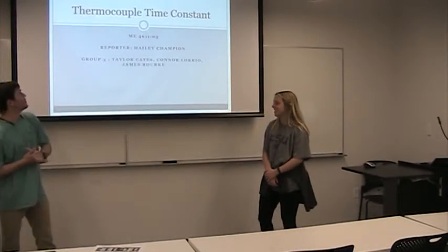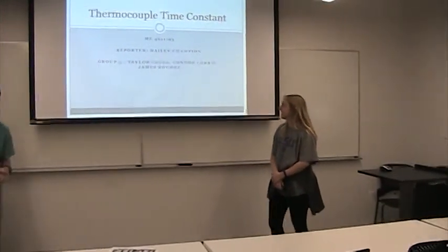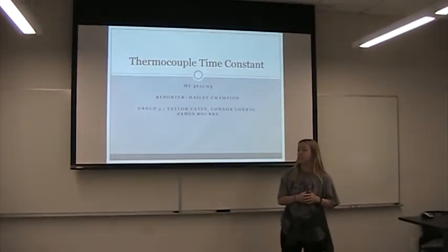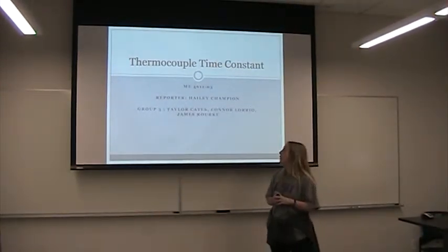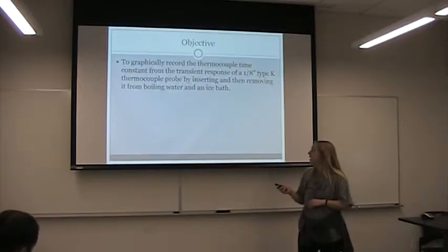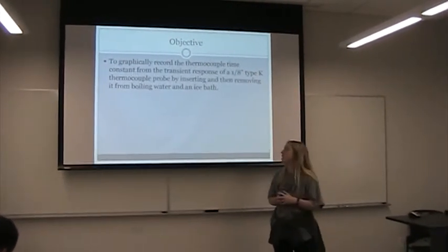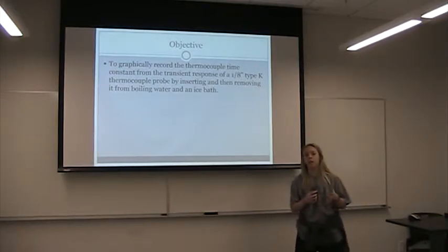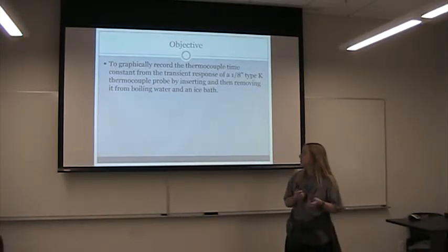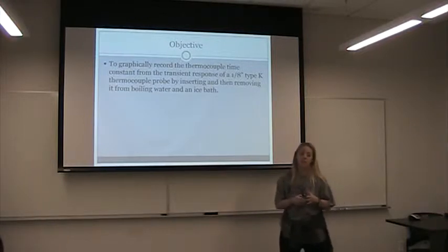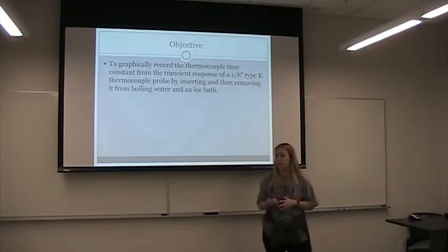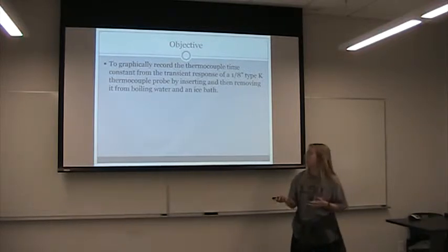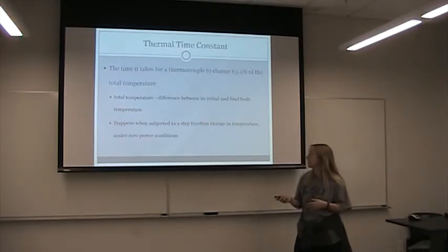topic on thermocouple time constants. Hi, I'm Hailey, and I am the reporter for Group 3, and I'll be talking about thermocouple time constants. So our objective was to graphically record the thermocouple time constant using a 1/8 type K thermocouple probe by both inserting it and removing it from either ice water or boiling water, which in our case today we are going to talk about the boiling water one.